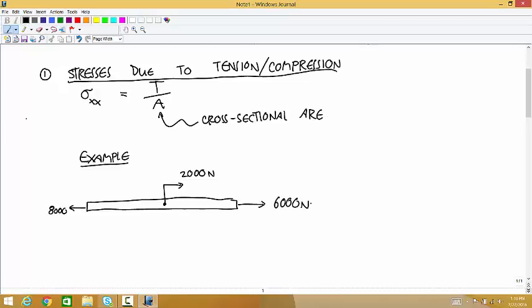I don't have this in the problem I'm looking at, but let's apply a downward force too, just to clarify what I'm talking about with the superposition principle. So let's say that there's also a torque of 1,000 Newton meters, and the downward force, let's say that's 500 Newtons. And let's say that we want to calculate the... actually, sorry about this one, let's move that torque to the end. So we have a 1,000 Newton meter torque going to the right at the right end.